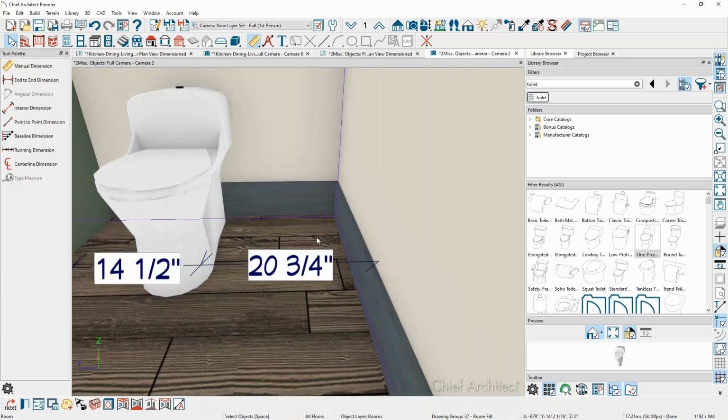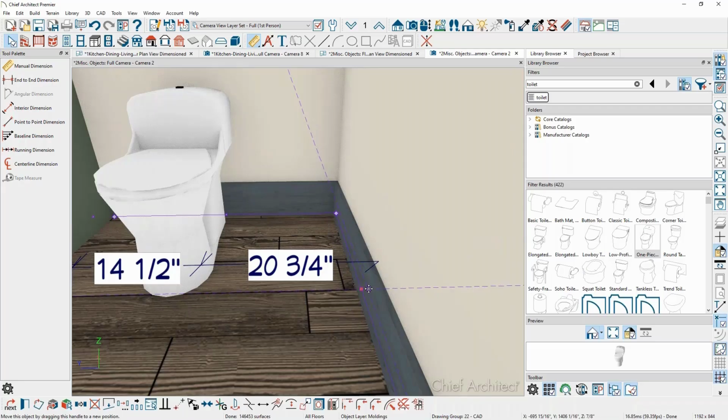So if I click in the room, in the bottom toolbar, there's an option that says Make Room Molding Polyline. So it's going to be that button. And when I click on it, it'll ask which molding do you want to detach from your room settings. In this case, I only have the base molding, but if I had a crown molding, for example, I could detach that. I'll go ahead and click on OK. And then when I click on it, it might be a little bit hard to tell, but in the bottom left-hand corner, it says Molding Polyline. So I know it's a freestanding object in the design now.